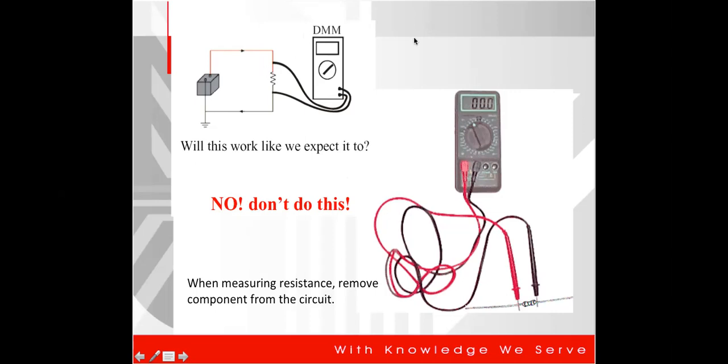So if your resistor is in the circuit like this, macam contoh tadi, you have a battery and then you connect it to the lamp. The lamp becomes your resistor, and you want to know how much resistance is at the lamp. So you take your ammeter and you put your ammeter here like this, and this will not work.